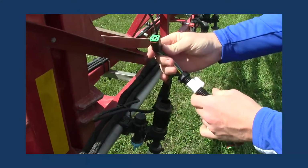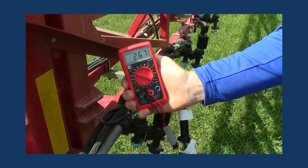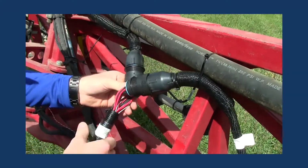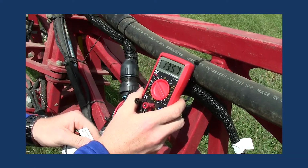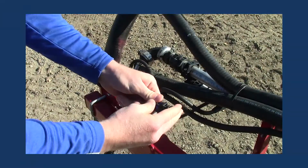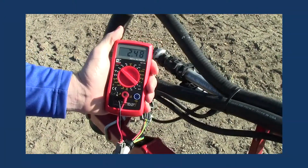The 6-pin diagnostic cable can be used to test high current power, CAN high, CAN low, switched in, and switched out. The 19-pin diagnostic cable can be used to test CAN high, CAN low, CAN power, high current power 1, 2, and 3, and also the enable pin. The terminator diagnostic cable can be used to test CAN power, CAN high, and CAN low.